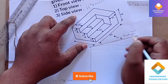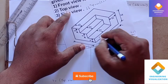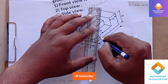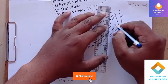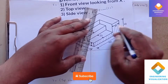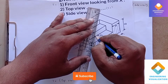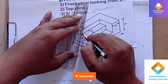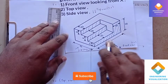Now I'll be analyzing the front view. To analyze which faces are visible, I'm going to shade them. This is how it is easy for us to identify which faces are visible from the front view. You can see that the L shape is visible from the front view, and then this rectangular face is also visible. I'm shading it. And this face is also visible from the front view. So these three faces are visible from the front view.